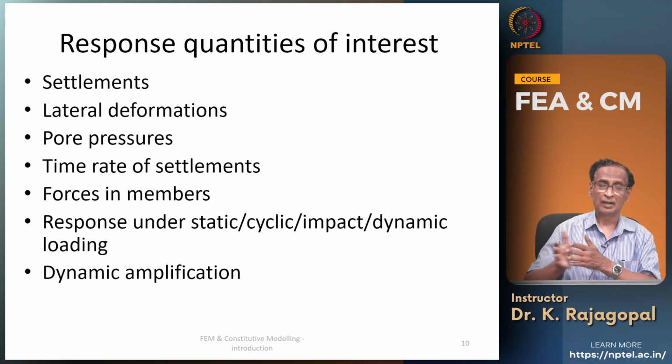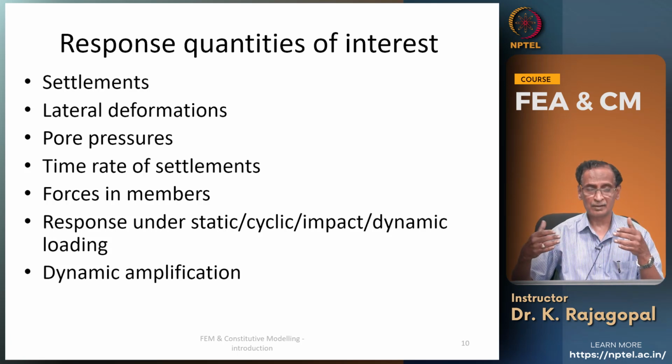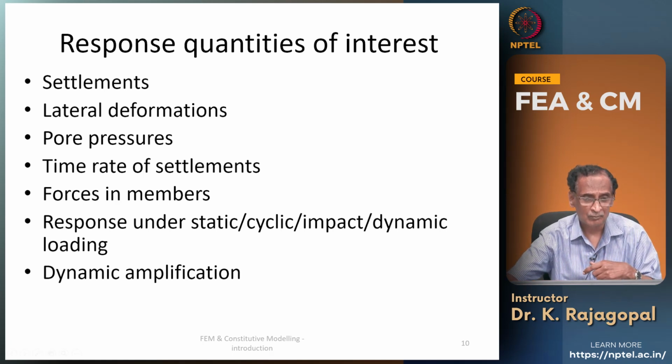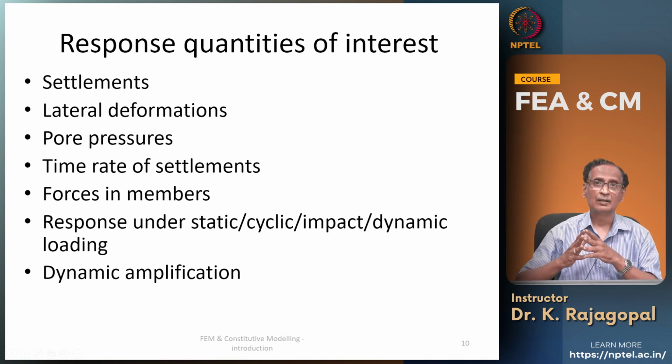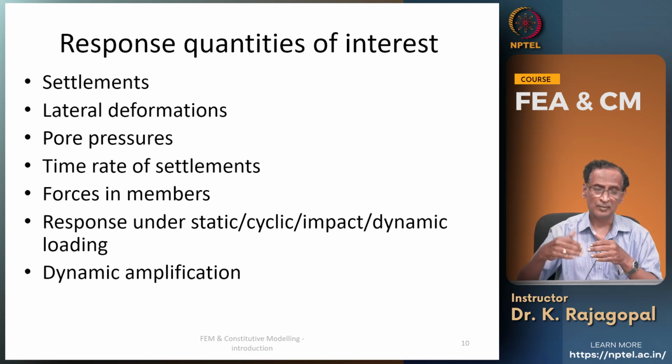And if you are doing any construction on soil with water, what are the pore pressures? And then if you are dealing with any soft clay, what is the consolidation, what is the time rate of settlement? Because this could govern our designs, and if you are not able to get rid of your settlements in a short time, you might want to go in for some ground improvement.